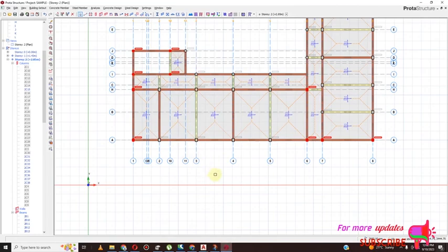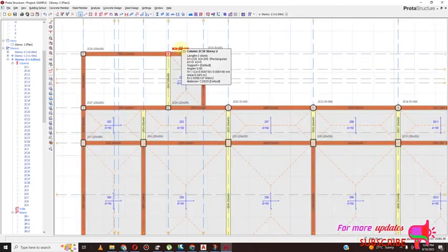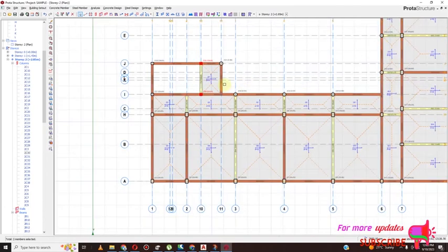The other important point is you should know that the stairs columns, which are going to hold the water tank, should be bigger than the other columns. You should have that in mind before when you're modeling. They should always be bigger than the others, because the water tank is very important and very critical.